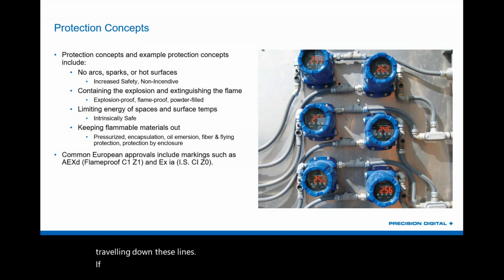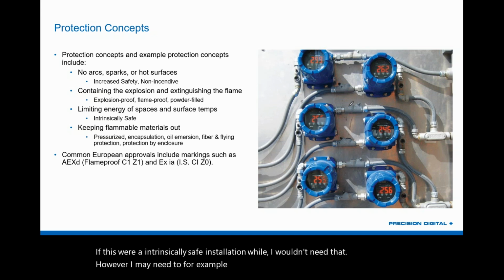If this were an intrinsically safe installation, well, I wouldn't need that. However, I may need to, for example, have barriers on all of my signals in and out, versus a non-incendive installation where I may not need the barriers because it's going to have different divisions that it's rated for. So knowing that protection method lets you know how you have to install these.